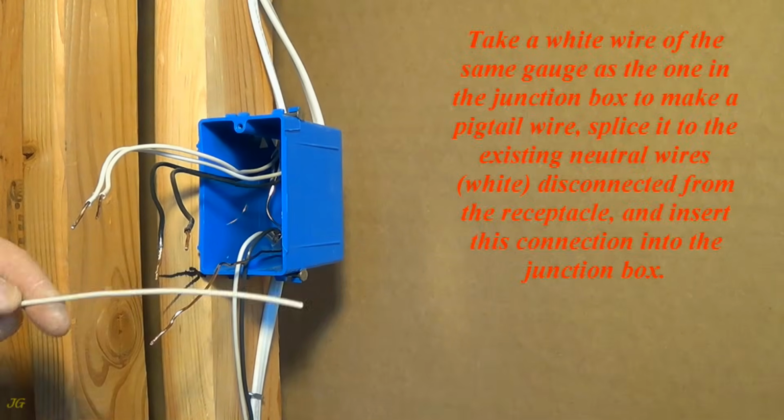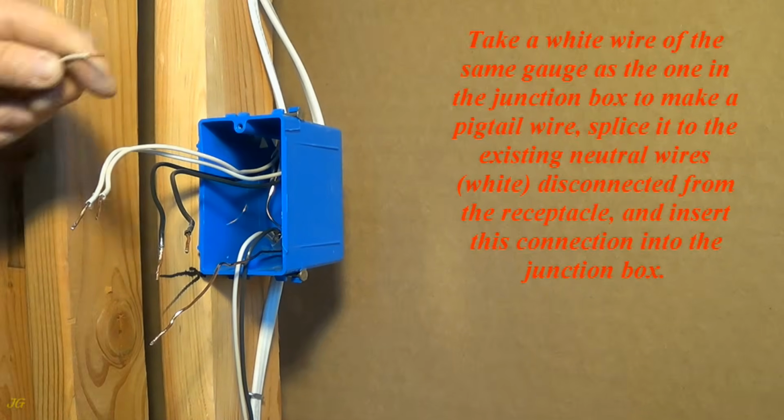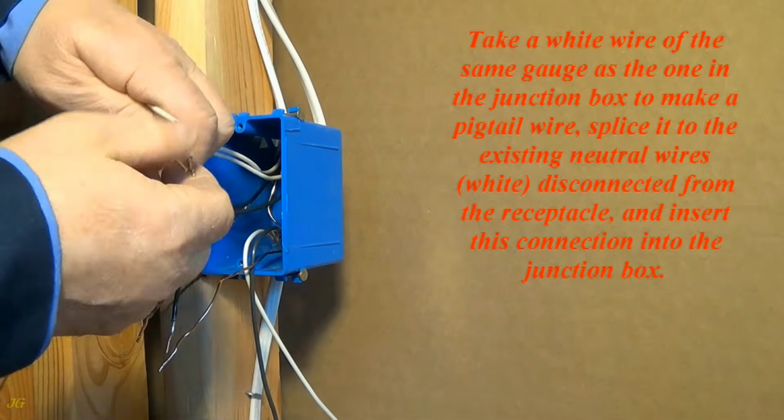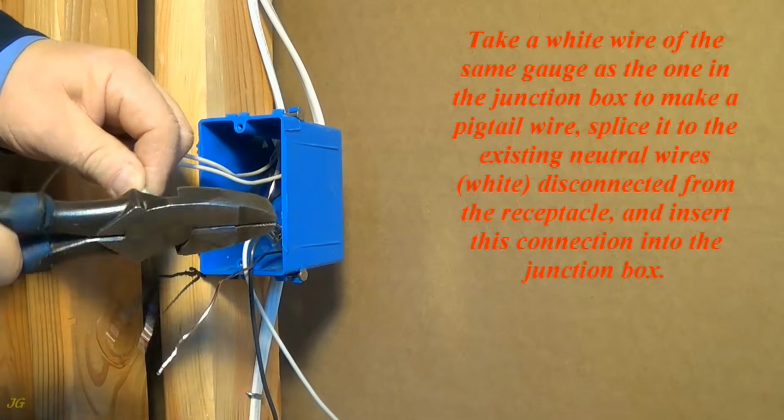Take a white wire of the same gauge as the one in the junction box to make a pigtail wire. Splice it to the existing neutral wires, white, disconnected from the receptacle, and insert this connection into the junction box.